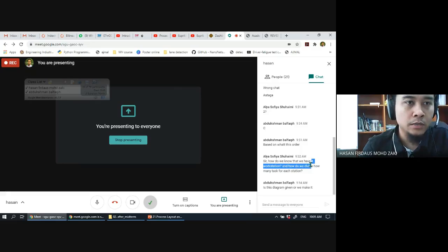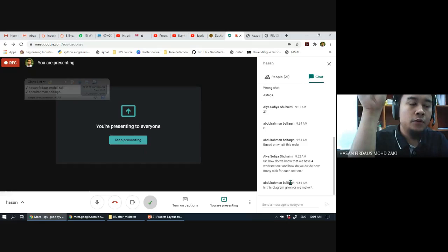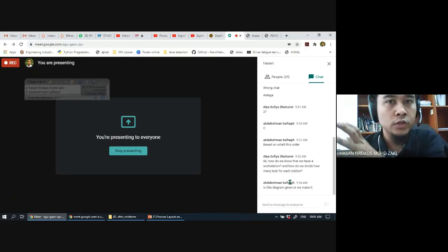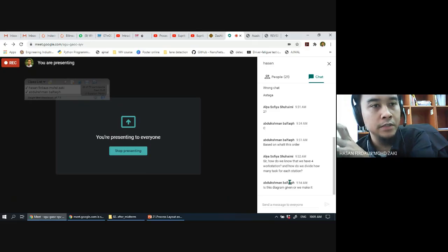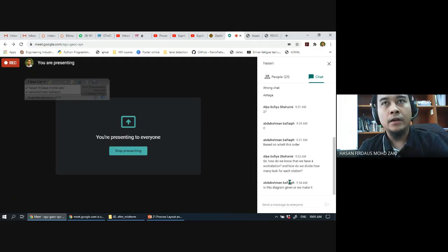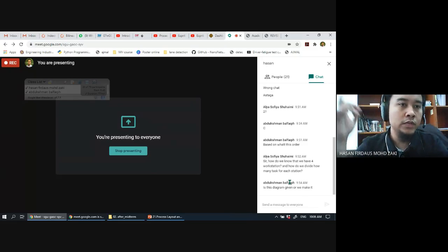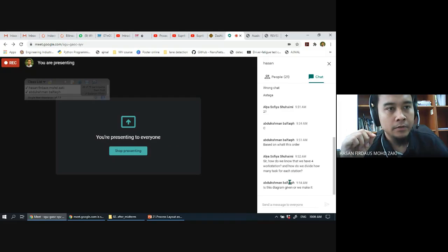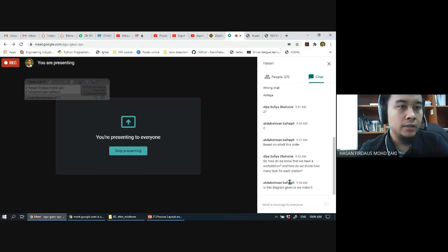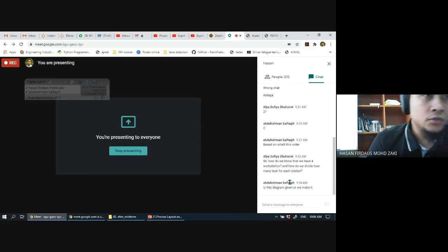Let's say you have a theoretical minimum of 4 stations, then you start with the first workstation. For the first workstation you go to the rank. Which one is first in your rank? Let's say the first rank is task F. Then you subtract it from the cycle time. If you have remaining time, you look at the next in the rank and subtract again, and so on until you cannot add more based on the cycle time. Then you take that as your idle time, and so on.